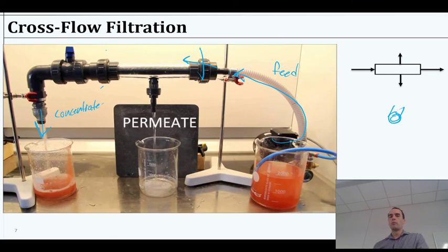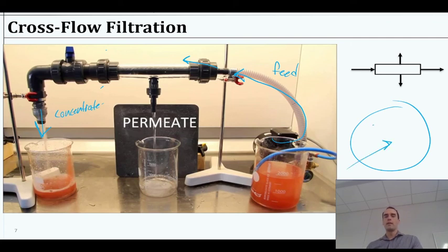Yeah, so I was meaning to come right back to that. The way the filter is working on the inside here is going to be the hollow tube is itself a membrane where I think the water's coming into the inside of it, and then some of it's pushing out, and this is the membrane surface. So the water is just continuously pushing from the inside of this tube to the outside and leaving the tube. Some of it, of course, passes all the way through the tube.